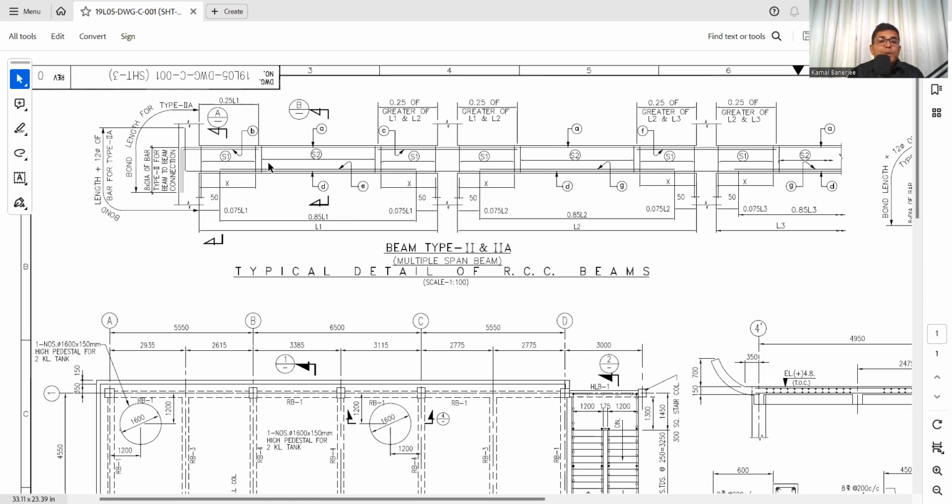So whenever we are preparing the bar bending schedule, with detailed calculation we will find out how to place the bar according to the splice zone. Here itself the bending moment is maximum, that's why the extra bar is provided. So here we cannot provide the splices; for the top bar we need to splice at the support side's opposite, that is at the midspan.